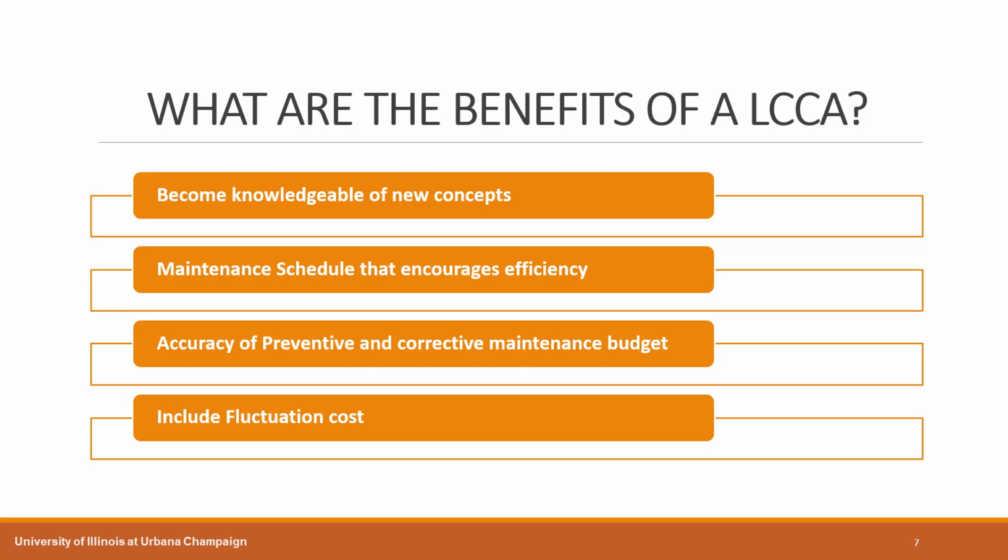What are the benefits of executing an LCCA analysis? A life cycle cost analysis introduces to the owner important concepts that are used to calculate the life cycle cost. For example, sunk costs, which indicate that those costs are not applicable to the analysis. Another benefit is the maintenance schedule that encourages efficiency. Owners and managers can design a maintenance schedule that doesn't interfere with periods of peak operations.